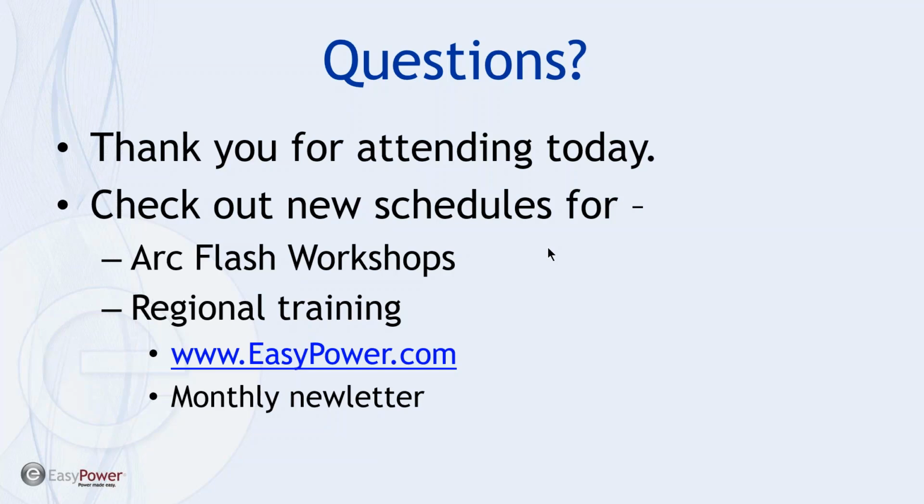So, is there a reason to use momentary current? Momentary current will automatically be applied to any fault that lasts less than 1 cycle. So the answer is no, there really isn't any reason to use it, because it gives you artificially high results. Put it the other way around: because the integrated method looks at the reducing current, it should give me a more accurate incident energy calculation. If I use momentary current, we actually get a faster trip time than we would see in real life.